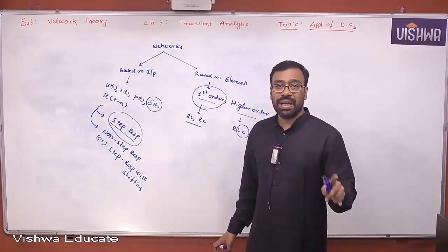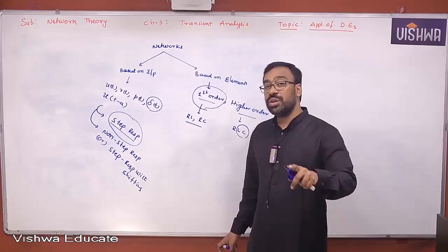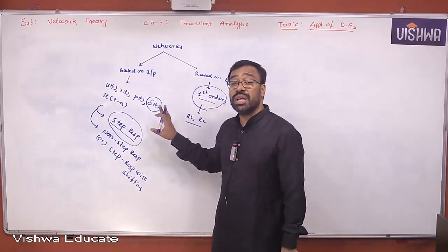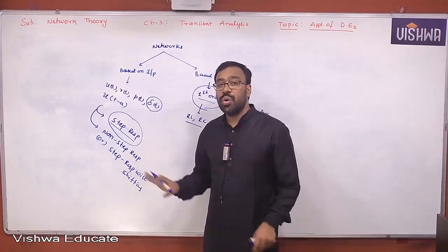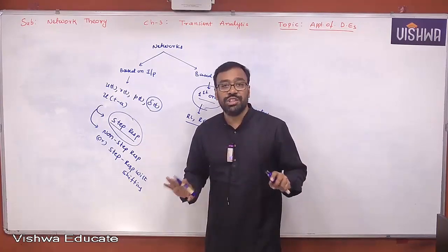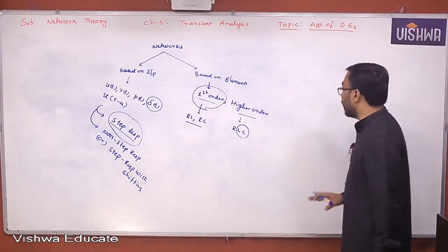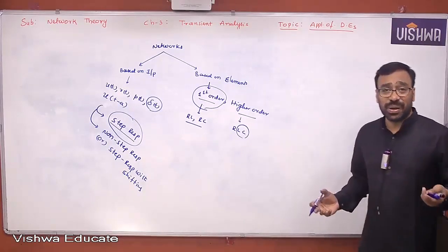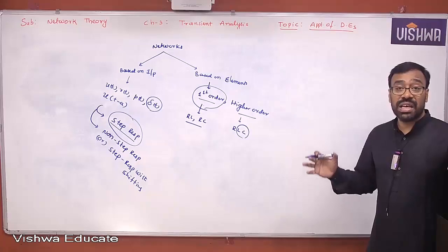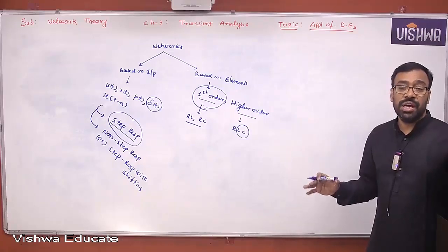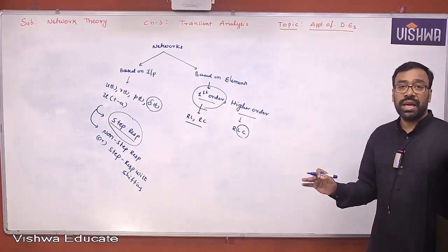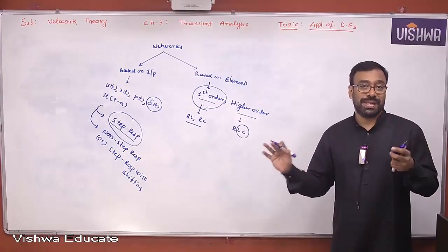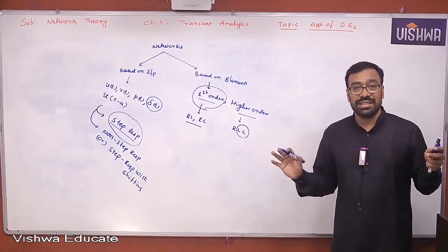So the method is applicable strictly to only which networks? Tell me all of you. The first order networks with the input given supposed to be only step input without any shifting. Understand all of you, okay? But you can ask me, sir, how can I solve the remaining circuits? The remaining circuits can be solved comfortably using the application of Laplace transformations. So that I will discuss later on, okay?